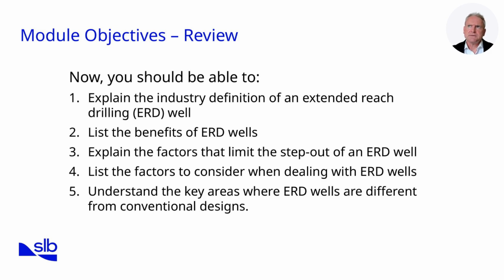Second, we looked at the benefits of ERD wells. We saw how they reduce subsea infrastructure, enable satellite field development, make nearshore resources accessible from land, and minimize environmental impact. Third, we reviewed the factors that limit ERD step-out, including hole instability, time exposure, drag, torque capacity, and fluid-related challenges.